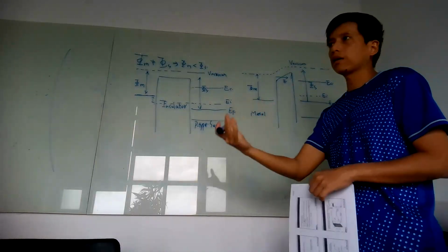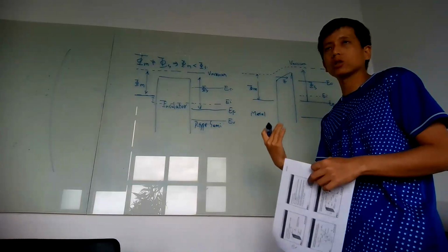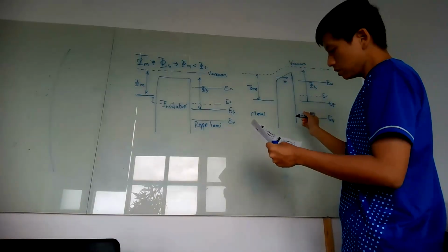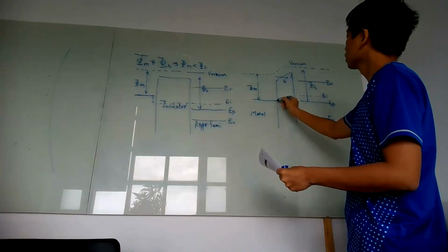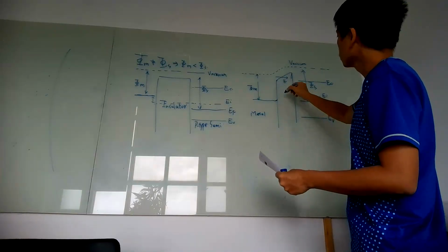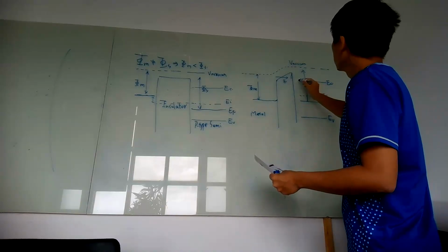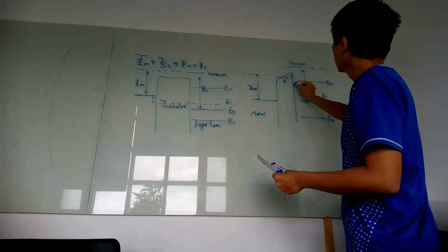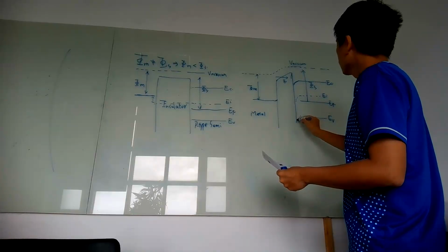If you have this condition, of course, once you get the electric field from left to right, that means you get a charge accumulation along the surface. So along the surface, we get a certain accumulation of positive charge in the metal, and we also get the band bending down here because we need to have the same slope along the surface.